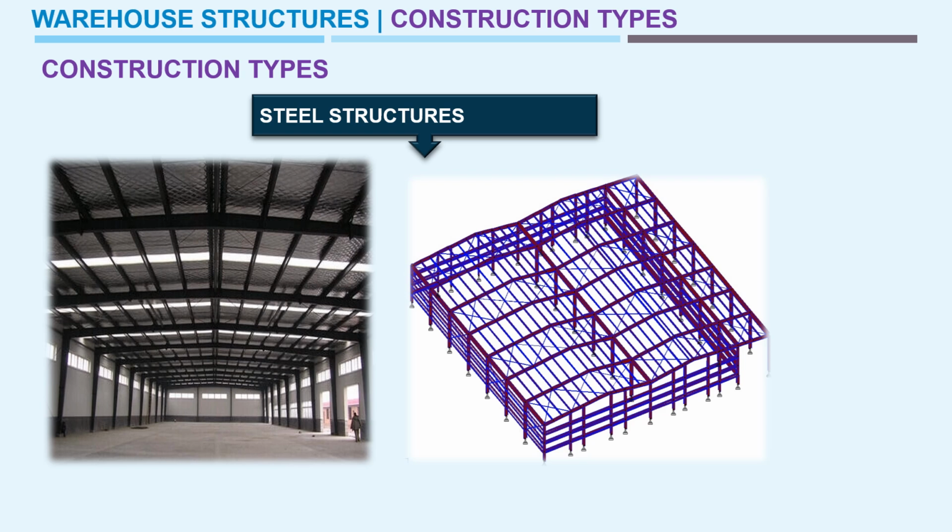The portal means the column and the rafter, which we call a portal, whereas at the end we provide some wind posts. You can see at the end there are two vertical columns that we usually call wind post columns. These help in resisting the wind forces, and the wind force distribution happens during wind action when a wind post is provided.